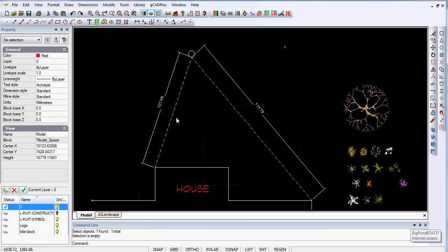Well, let's imagine that the rear of this house here has an existing tree some distance away from the house footprint. What we want to do is to accurately locate that particular tree. Let's imagine it has a fairly substantial trunk, and we can measure from the corner of the house here to the front of the trunk, and from the second corner of the house way back to the same point.